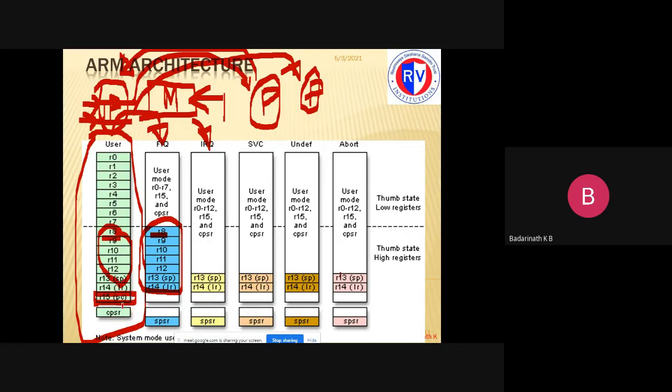Same thing is the CPSR register. CPSR holds intermediate important information about your program. Carry flag, zero flag, overflow flag, all this information will be there, and whether you're in Thumb instruction mode, so many things are stored here. So when I go to another mode to execute another program relevant to some other service to the device, the CPSR content should not be disturbed.